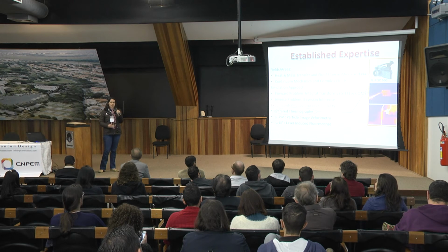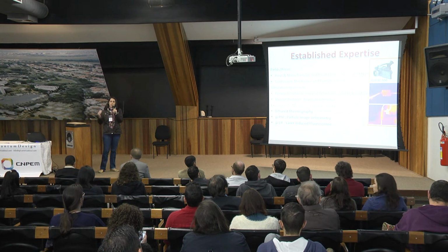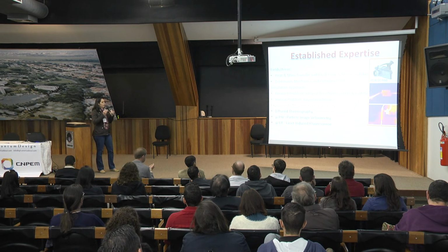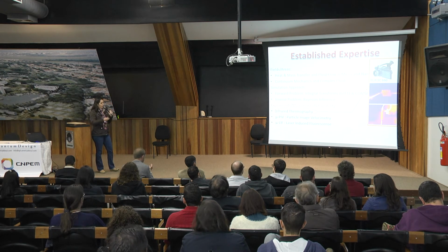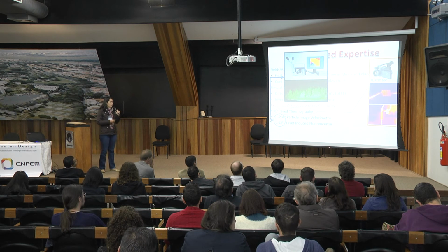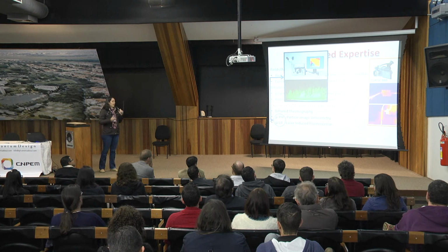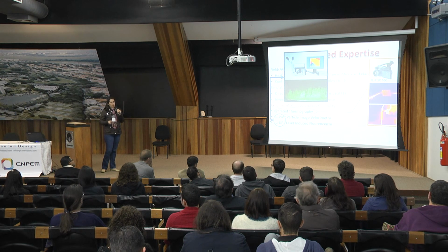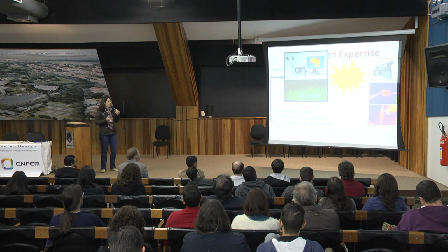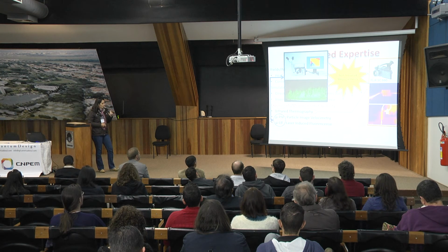So we measure the temperature at the external surface of our microsystem, of our substrate, and we are able to make inferences about what is happening inside the microsystems using a mathematical model that couples what happens in the solid and in the liquid and in the whole structure. And also we have some experiments using particle image velocimetry and laser-induced fluorescence to measure the velocity field and the temperature field inside the microsystems. So those platforms are non-intrusive measurements, and we use them as much as possible in our experiments.